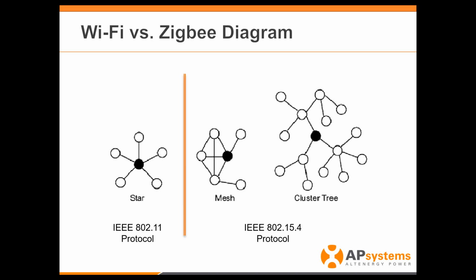I can see him there, but he can't hear me. So I'll talk to Cameron and say, Cameron, ask Ed a question. Cameron will ask Ed the question, Ed will reply back to Cameron, and then Cameron will reply back to me. This is what we call the ZigBee network, or the self-healing network. This is a recipe for success, and it reduces any kind of issues on the roof as far as communication is concerned between the inverters and that gateway.